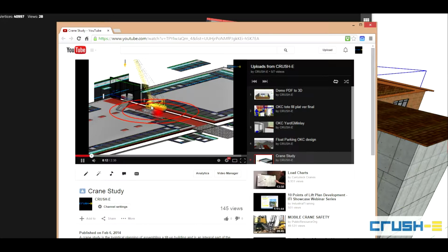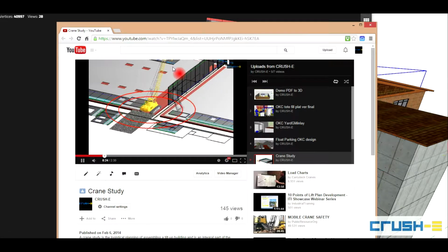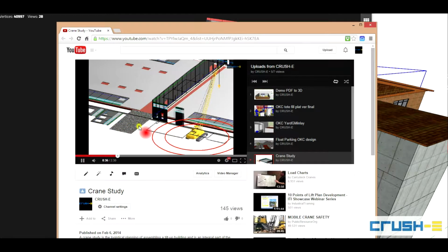And you can see how the animation shows the panel sequences, where they're laid out, and then where we're going to put them in. There's a lot more information in this model that we couldn't fit, and for instance, animating the crane to pick up each and every panel would have taken forever, so it wasn't a part of what we wanted to do. So now the interior line is the safety line for the guy in the cab, and the exterior line is as far as that crane can reach for the heaviest panel on this project, which happens to be this last one that sits across here. So we built a ramp in, got the crane in there, poured the slab back by the time we had all the panels up all the way around. So that's another technology that we use.